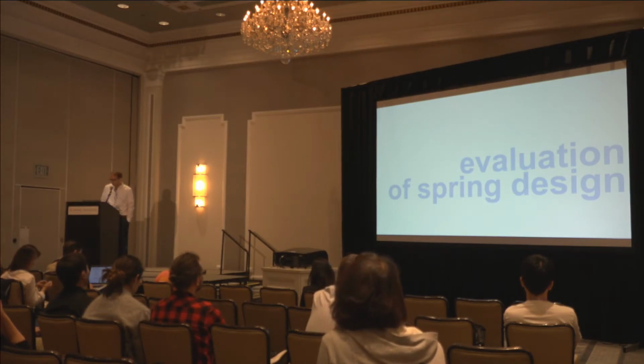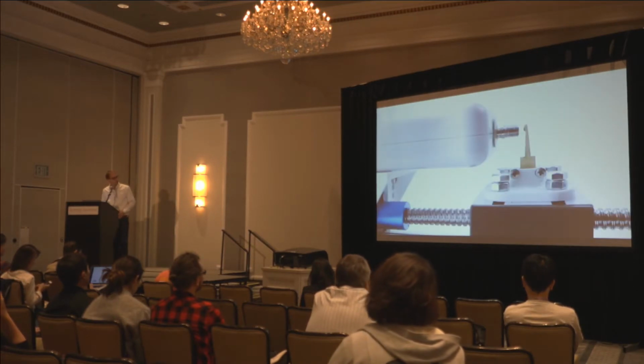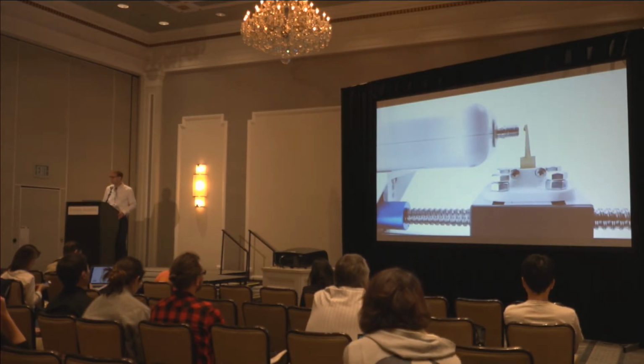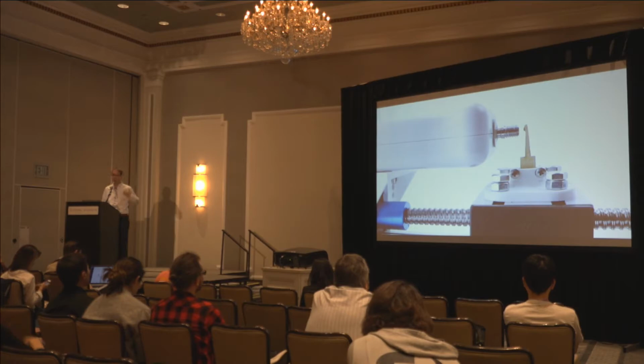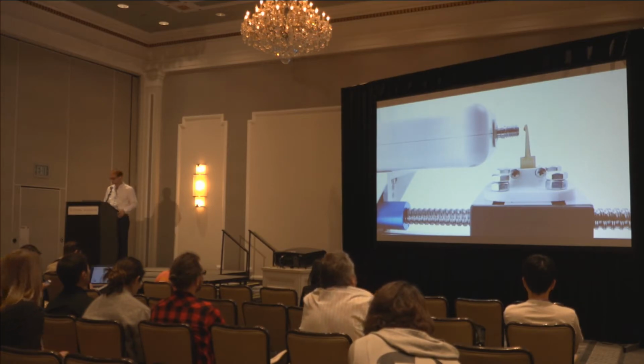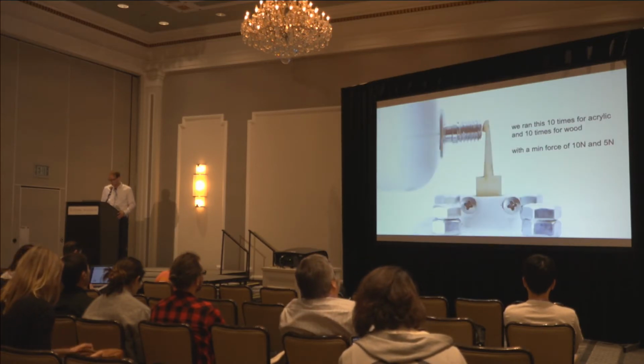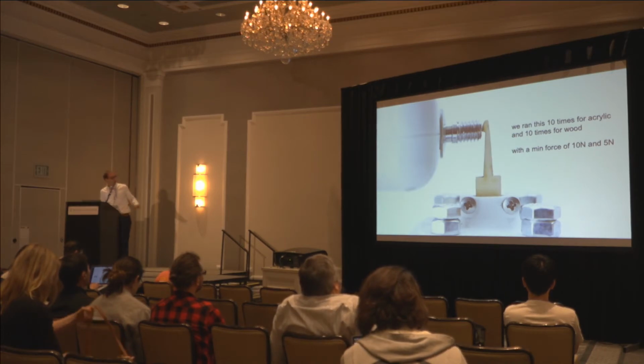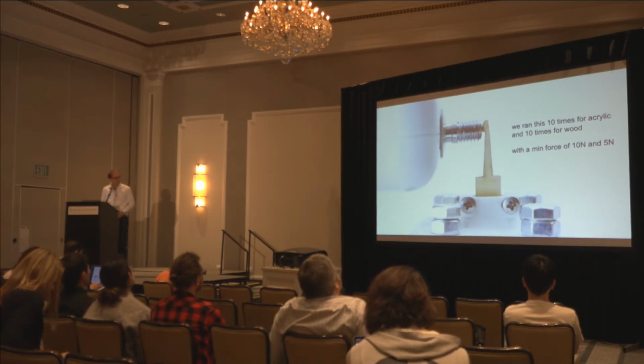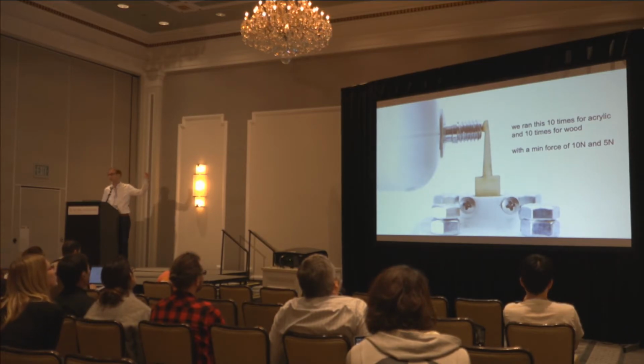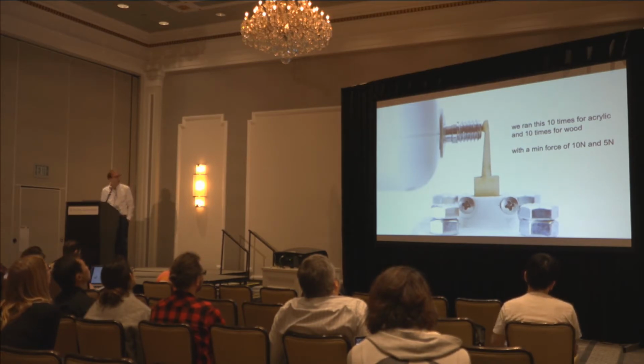So we evaluated the system both on a technical level and on a practical level. So on a technical level, we wanted to find out whether the springs that we generated actually perform how we hope they should perform, like whether they are performing to the spec that we set for them. So we slowly pushed a force sensor into the spring, and you will see that it slowly pushes it up till the moment that the amount of deflection is reached that we had intended it to be, with the force that we required it to be.